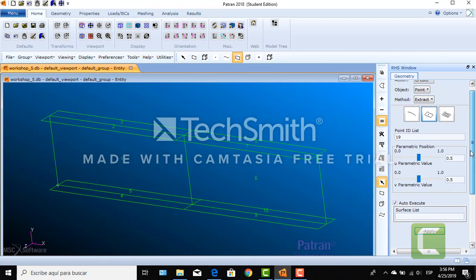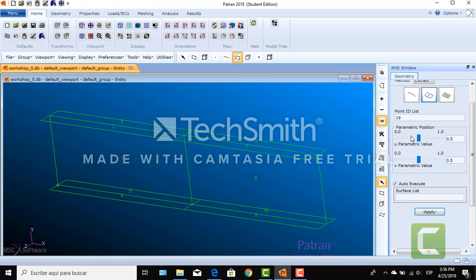We're going to be working on different values on the parametric position window here. We're going to leave the bottom one as it is at 0.5, but the top one we're going to set to 0.25. The surface list we're going to leave at auto execute, and the surface list is going to be on the first surface, and on the 6th surface too. As you can see, we have 1 point here, another one here.